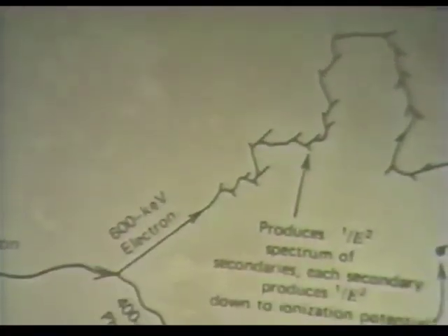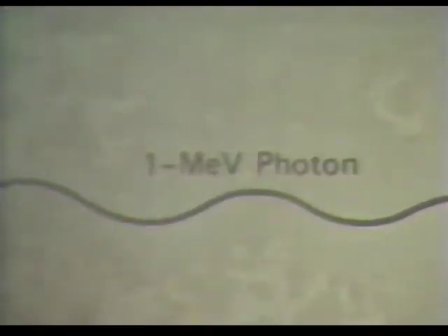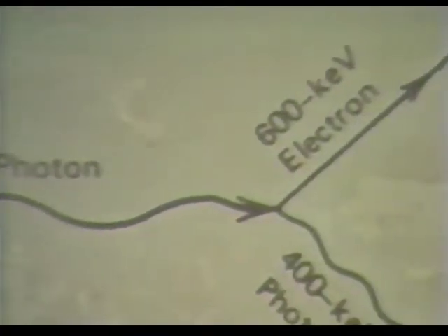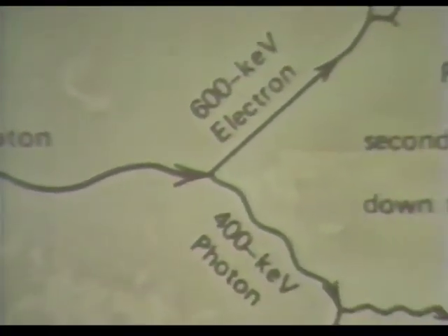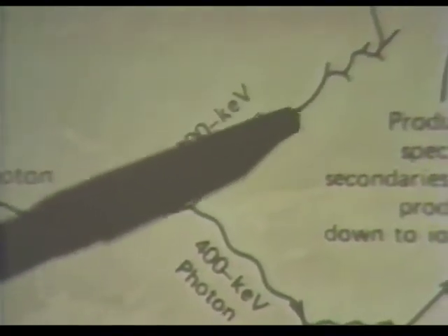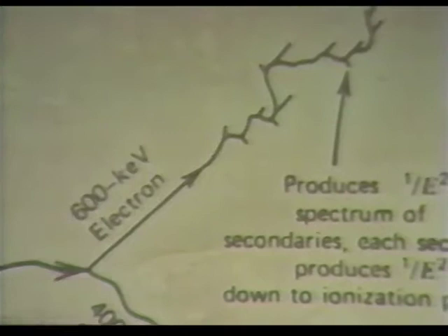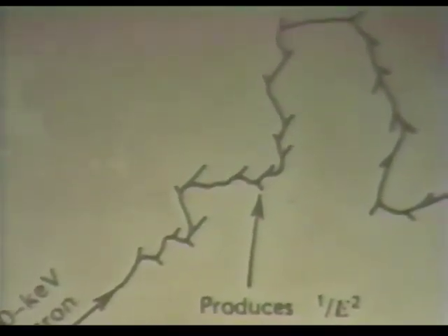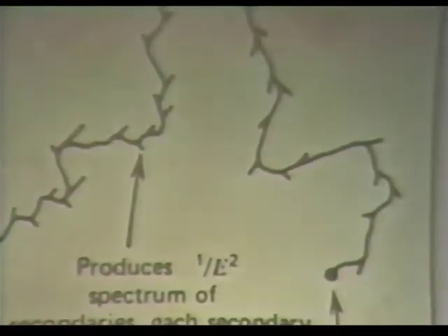Now let's look at a Compton interaction. Here comes a 1 MeV photon. Now what happens to it? It smacks into an orbital electron in one of the atoms in your oxide. And that electron that it hit goes flying out of orbit. And it does the same thing to others, and finally it uses up all its energy knocking electrons off of atoms.